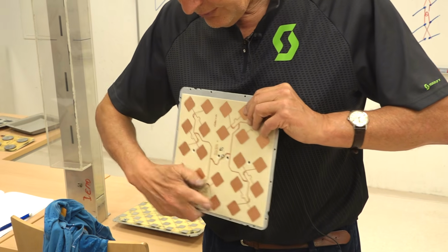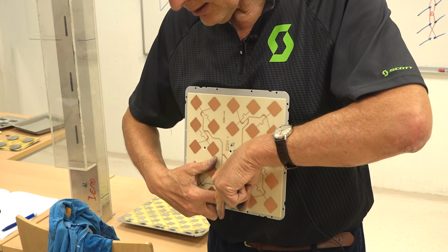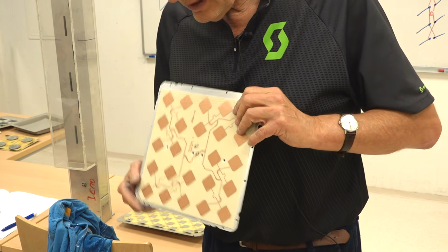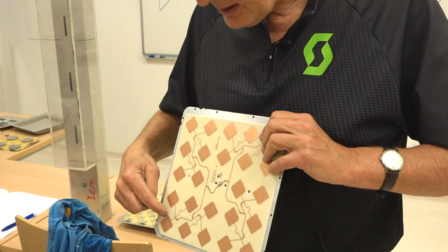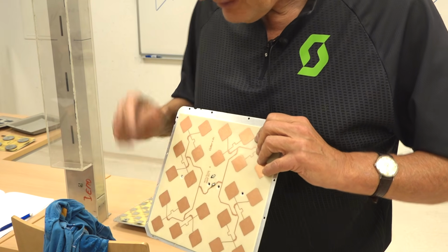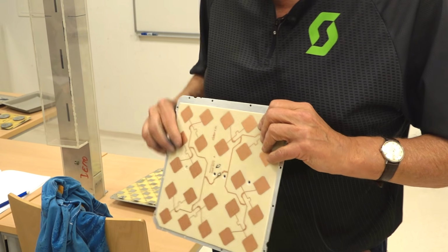to get the phase shift between this mode, and this gives you circular polarization. So this is this array. It was made for circular polarization with many patches, and the patches themselves are transforming circular polarization into a linearly polarized mode in these feed lines here.